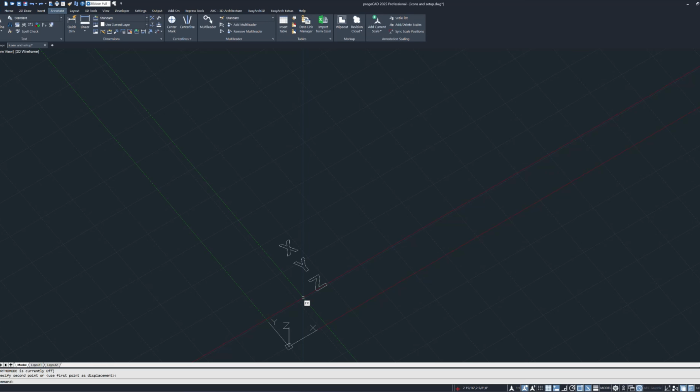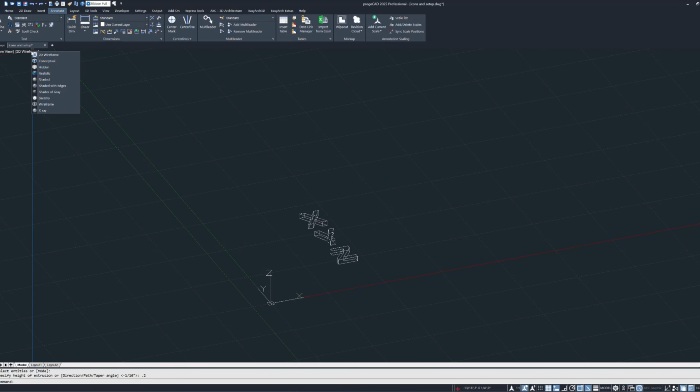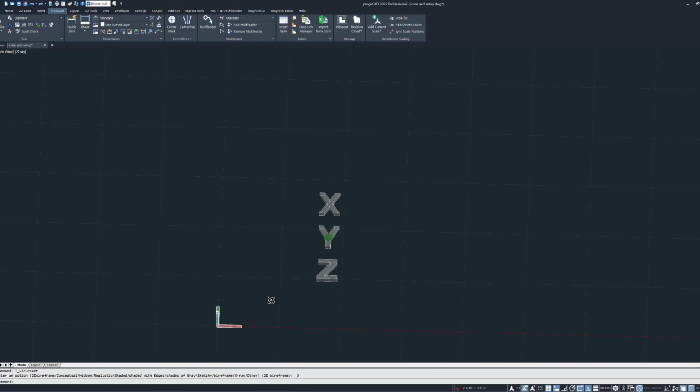Since our text is now exploded as individual line elements, we have to use a command called extrude to get them into a 3D object. This command expects only a height, but can also accept a point in space, which is not as precise. You will notice a short line that demonstrates the height. Our inputs will rely on precise measurements to align the text within a dimension cube, making the process easier. We will spin the model so we can demonstrate that all surfaces are indeed solids.